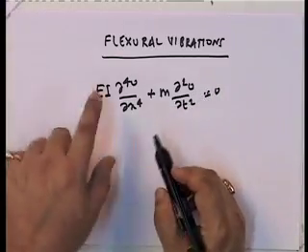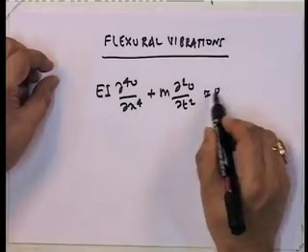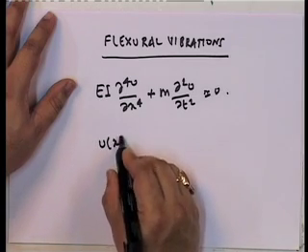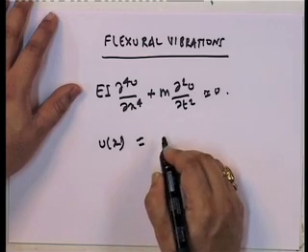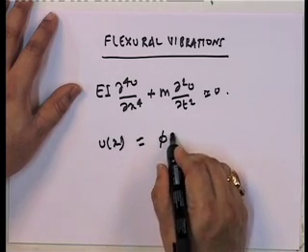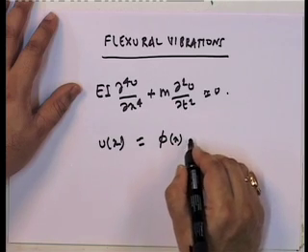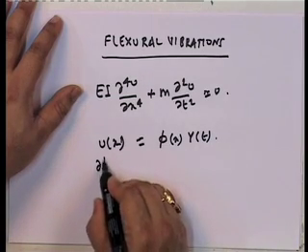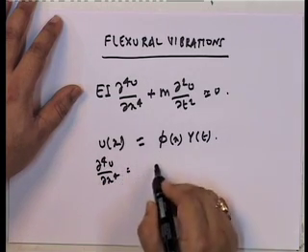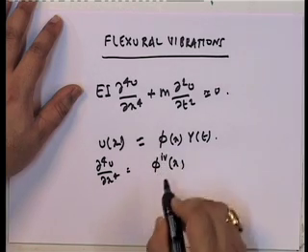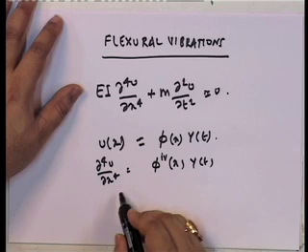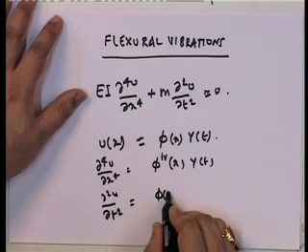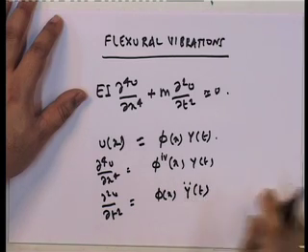In actually it is d squared, but since EI is a constant, we can take it inside. Okay, so this is the equation, and v of x, which is a lateral displacement, we take it equal to phi of x and y of t. So, if you look at it, the fourth order derivative would be equal to the fourth differentiation of phi into y of t, and del squared v by del t squared is equal to phi x into y double dot of t.